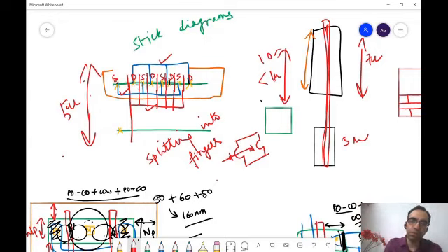Yes. Then for this part, because the drain is shared, this is the drain, then that becomes the source. Now the source is shared, so the other part becomes a drain. That is why we connected alternate contacts, alternate active regions, through metals to get source and drain nodes. So this node is the drain node, this node is the source node, and this node is the gate.